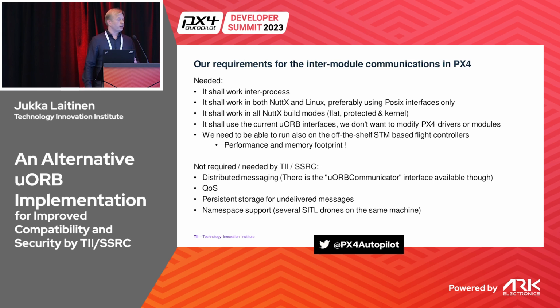So we started thinking that we probably need to replace the whole uORB with something that can actually work inter-process, and collected some requirements for that. Obviously, working inter-process is a must for us. It should work in both NuttX and Linux, because we are running PX4 in both of those environments.